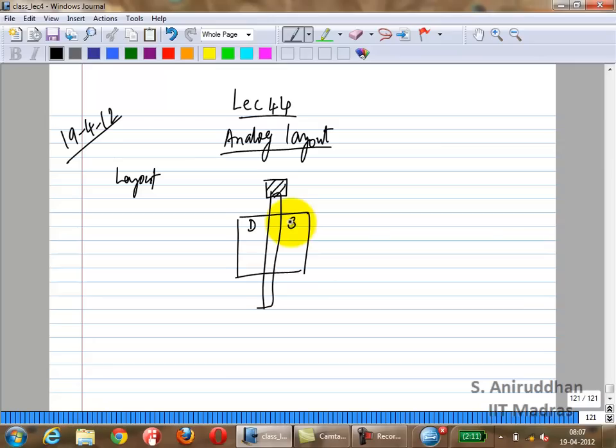So you get the IC fabricated, and that includes the diffusions, the gate polys, metal lines which connect to both of these, and interconnections between different transistors in the circuit. Eventually you will go out to pads, usually the external periphery of the overall IC, that get connected to the external world using a bond wire and through the leads of the package.